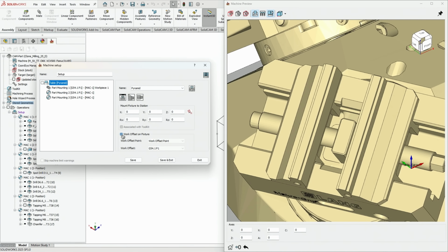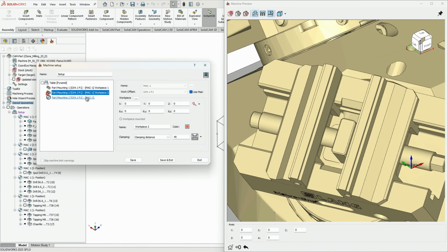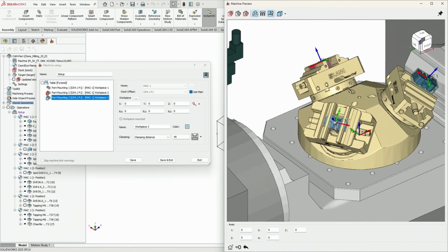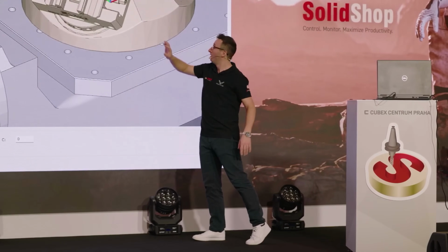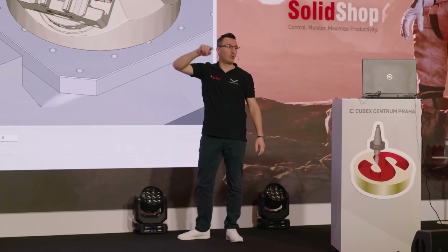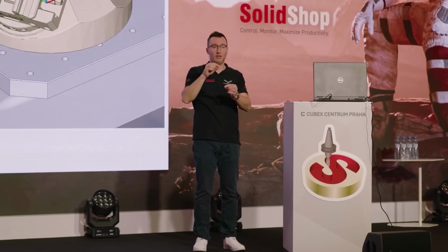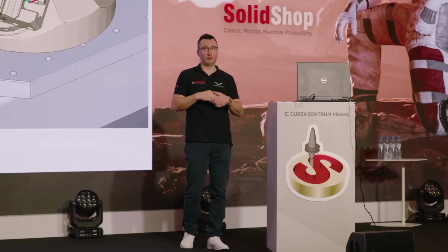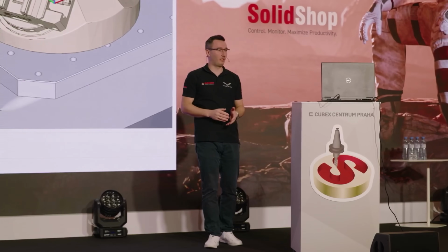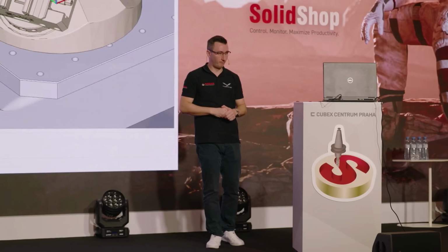Work offset on fixture. Just use it, select which one it is, add the clones. Now what will happen, we still don't show it visually, but all these 3 will be just the mounts. But the work offset will be directly on the fixture. So the shifts will go from each individual, these 3, while you're doing only the work offset, simplifying the setup only on that point there.